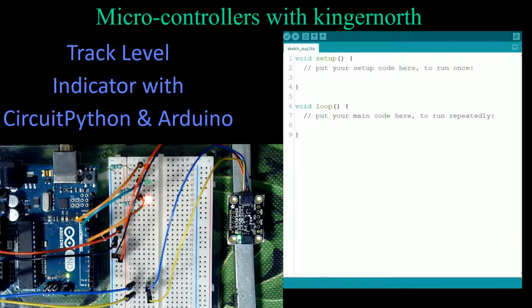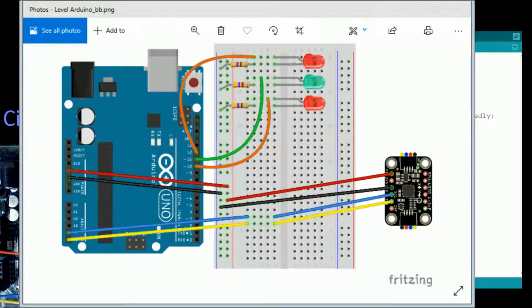So the first thing we're going to do with this is look at the wiring for the Arduino. So let's see what we hooked up and what we're using. I'm going to show you this here. This is my Fritzing diagram. Here's my board. Now, when we look at my board, you'll see there's a plug in the end of it. I have a cable that allows me not to have to use the pinholes that are built onto it. Basically it's the input voltage, the ground, and the SCL and SDA pins, which are the I2C communications that are connected back to the board.